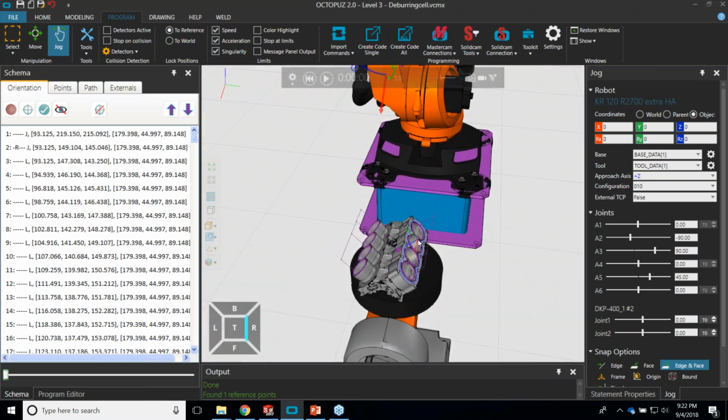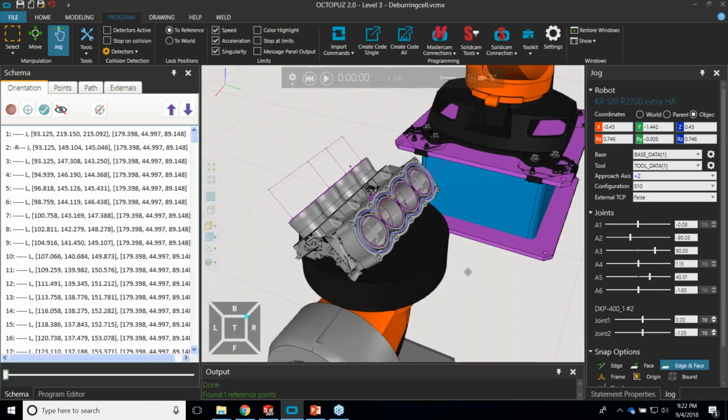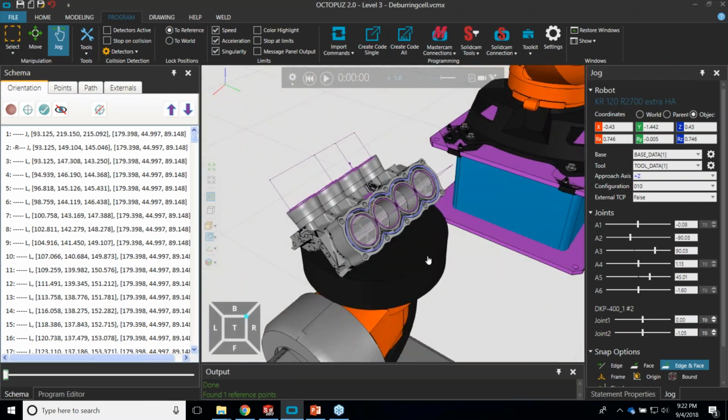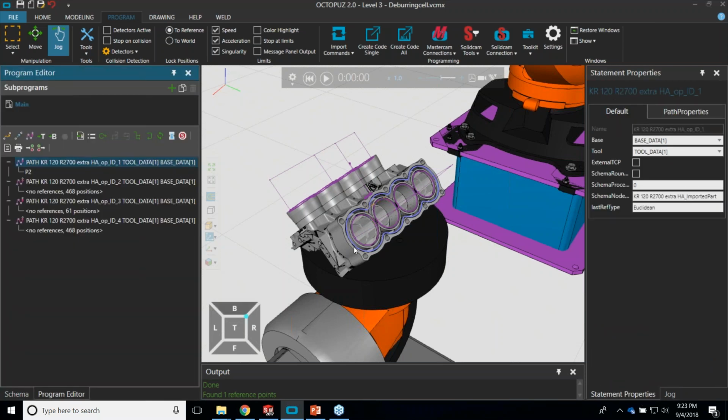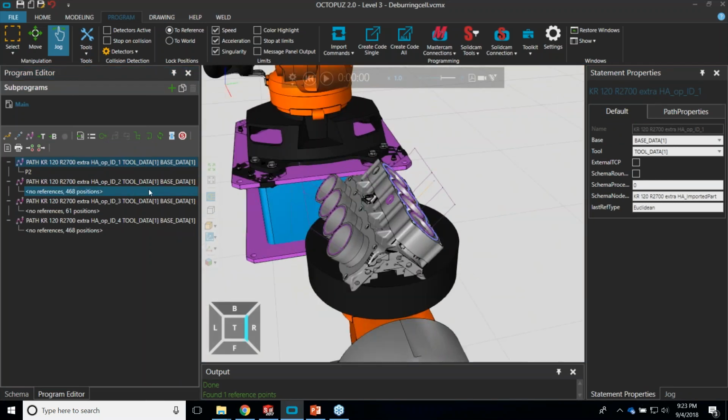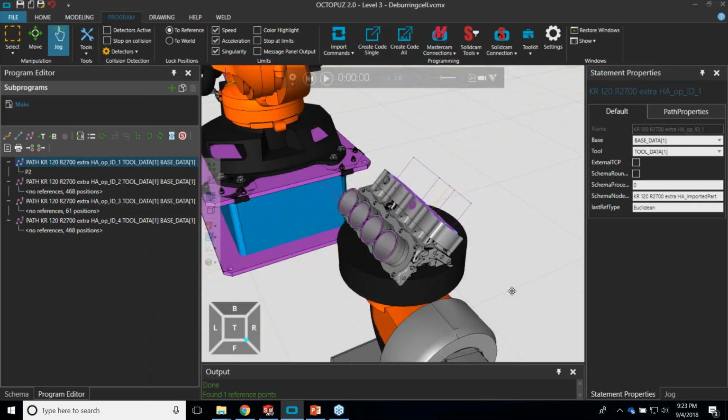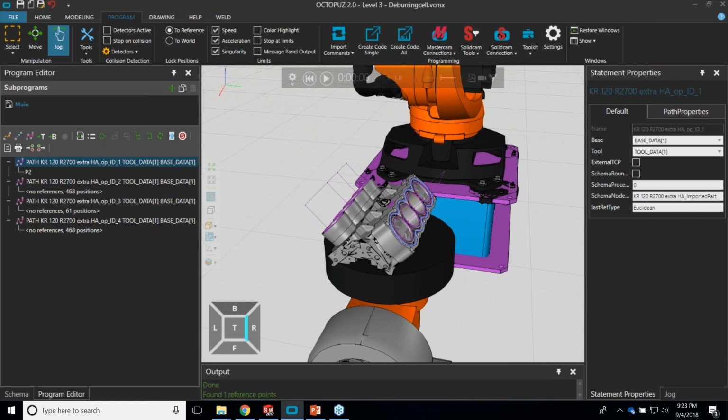This one in particular, it's hard for me to say because I'm only now just starting to play around on robots myself. But I'll give you an example. So to program this in SolidCAM probably took an average user, what would you guess, Kevin? I mean, to program paths like this would take maybe half a day. Well, I wouldn't even say that long to do the deburring side, but if you were to actually program that from the pendant, are you looking at a good 8 hours worth of using the point-to-point pendant? If this is a brand new program, I would say this is a day program at least. Okay.